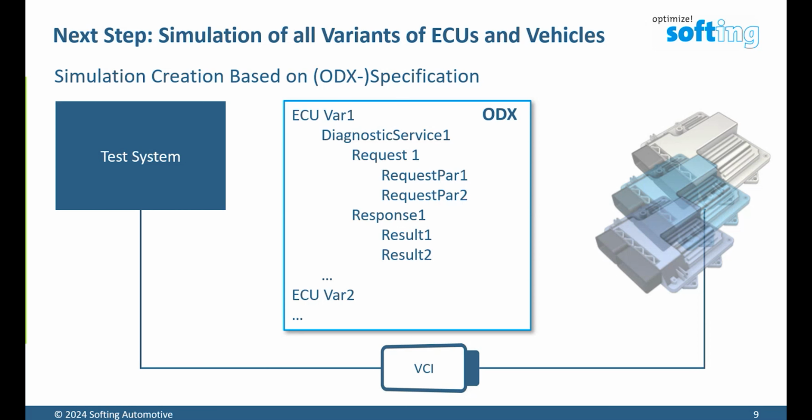So with the help of the ODX files, you can solve that problem. You got the ODX files, you can test with the ODX files. You have then, in this case, 3 or 4 months time. And then later on, the real device under test, the ECU, comes, and the tester is already tested. All the failures from the testers are, let's say, solved. So that makes the thing much, much easier, you save a lot of time, and you can raise the quality of the whole process. So ODX is a really big thing in this case.